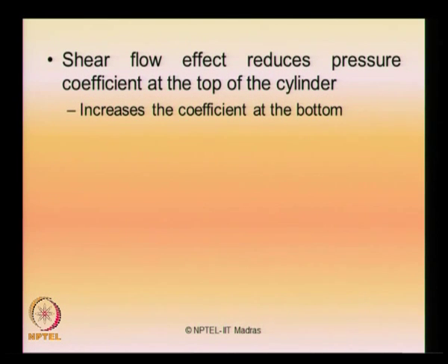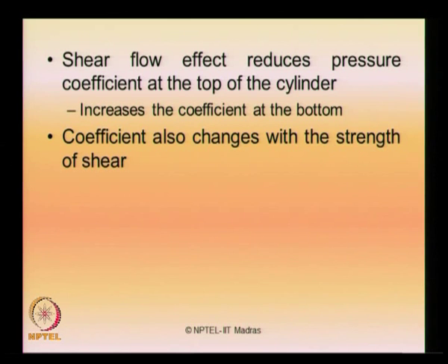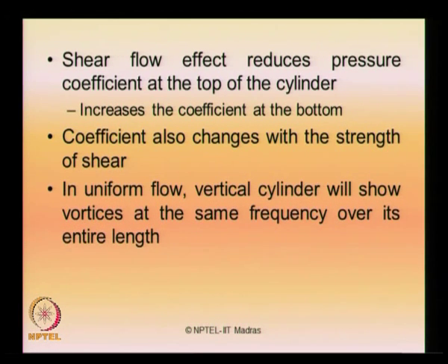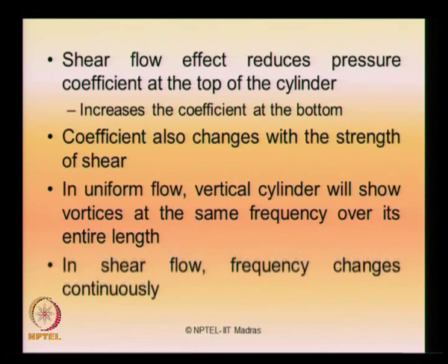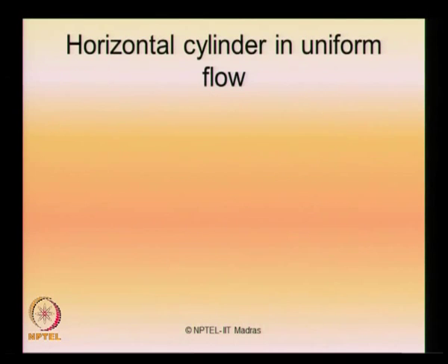The shear flow effect reduces the pressure coefficient at the top of the cylinder, but the coefficient increases at the bottom. The coefficient also changes with the strength of shear present in the medium. In uniform flow, the vertical cylinder will show vortices at the same frequency over its entire length. In shear flow, the frequency changes continuously.